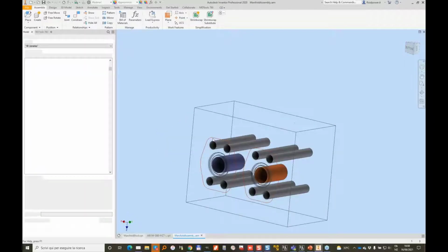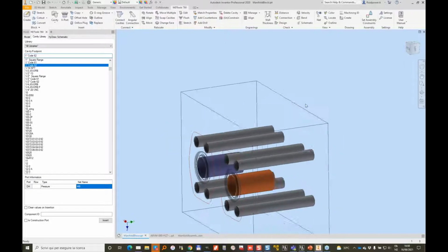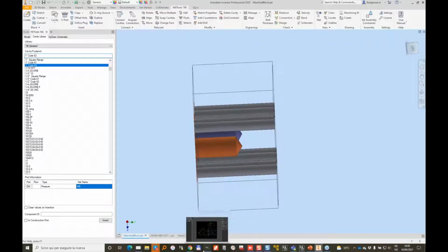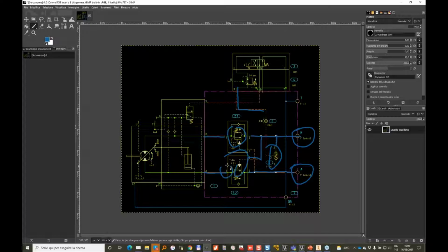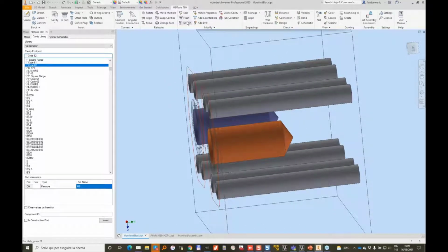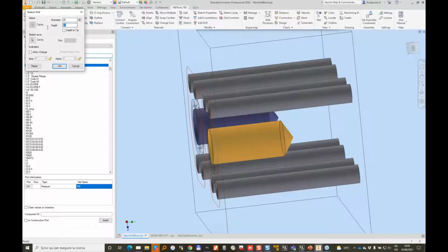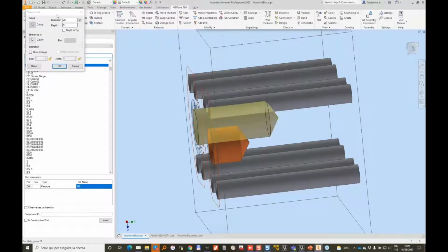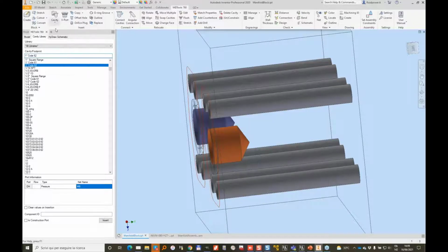And we go back to our block. So if you remember, there were two counterbalance valves. The counterbalance valve was linked on port 1. This is nice. It's a T2A, so we can put it directly opposite on the flange, having the one port on the motor side. So let me reduce a bit the depth of these drills. Let's say I just need 20 millimeters. And same here, stretch, select 20 millimeters.